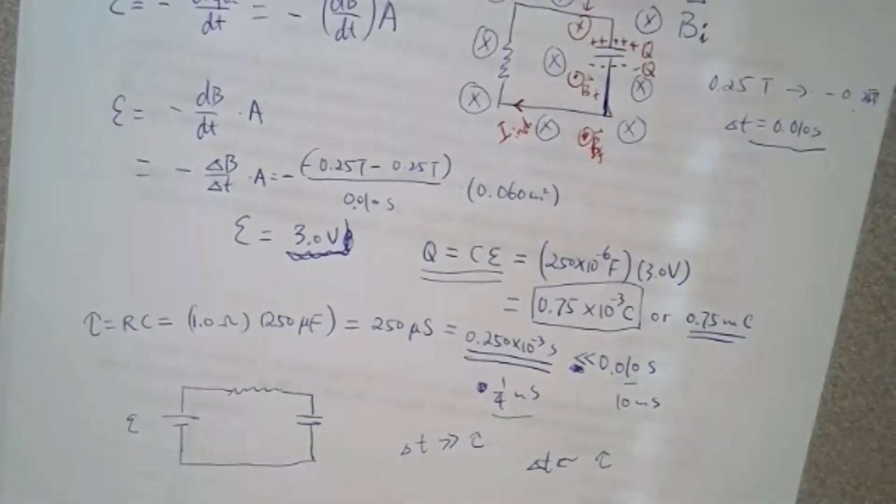And for this week's lab, we'll take a look at the charging process of an RC circuit. It takes about 4 times the time constant to get more than 98% charged. So after 4 or 5 time constants, we can say your capacitor is approximately fully charged by that point.